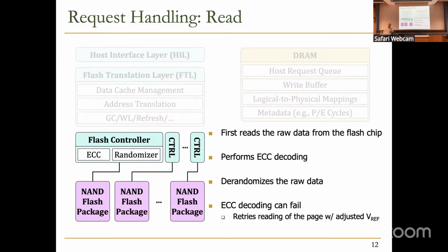Yeah, that logical to physical mapping has actually been stored in the NAND flash chip. But in order to avoid accessing the flash chip to get the L2P all the time, we move it to the DRAM. But when we shut the system off, it actually needs to be written back. And there is a procedure where people update that logical mapping online as well, so we don't keep all the updates until the end, right?